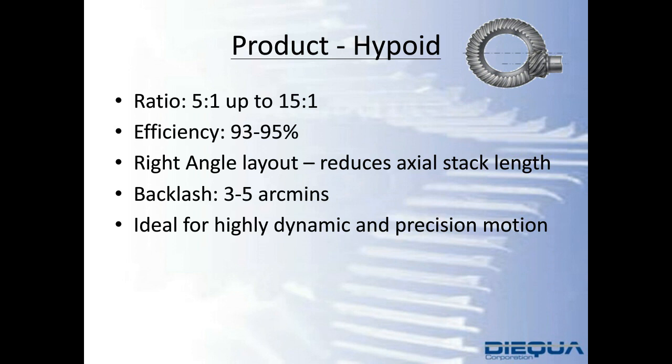These units, because of the spacing and the output, have a good amount of distance between the two bearings. Two bearings that are sitting right next to each other have a decreased capacity axially, primarily radially, to support outside forces. So by having an increased distance between the bearings, you'll see an increased tilting capacity. All right, so that's good to know.